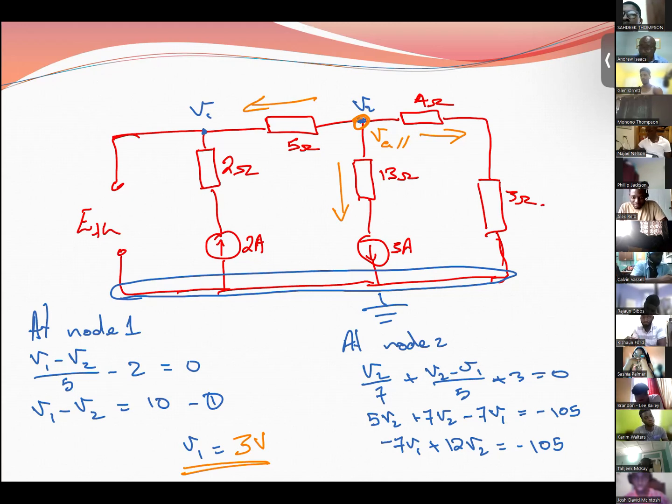So we have 3 branches attached to node A. What's the current in this branch? 3 amp. Good. So we have 3. What's the current in this branch? V2 minus... No, Mr. Reed, note there's no more V2 and V1. It is 1 node that we're looking at, and it's VA.